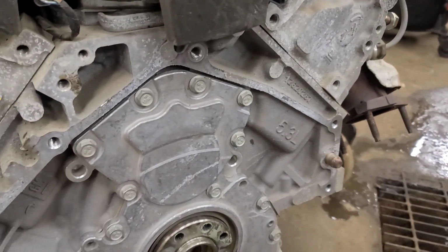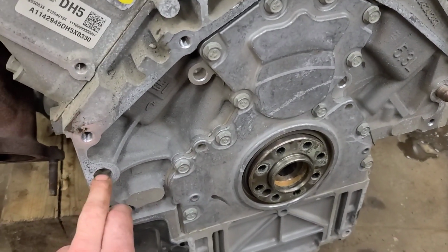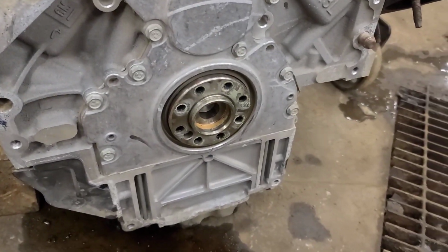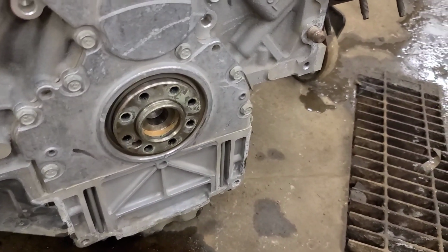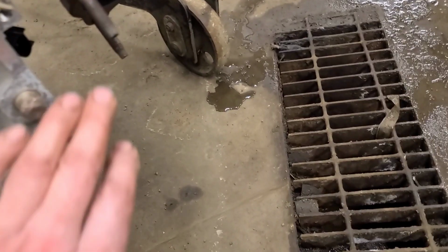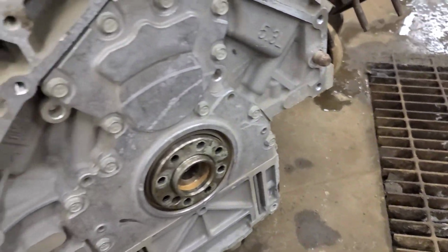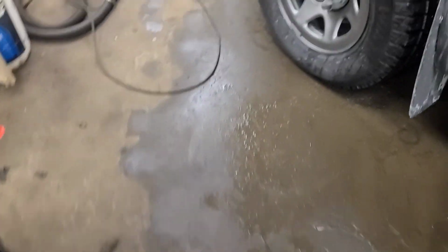I've got all the bell housing bolts out now. I see a dowel pin missing on this side, so we'll have to make sure we put one from the other engine in there. I got the torque converter bolts out, starter out, exhaust disconnected, wiring harness on this side disconnected. But I'm going to pull the intake off, like this one here, because I think that'll give us a little bit more room,